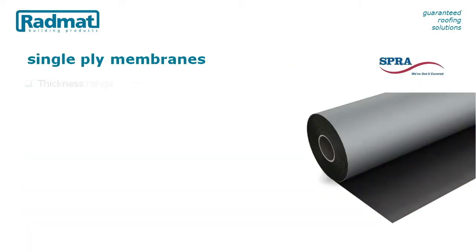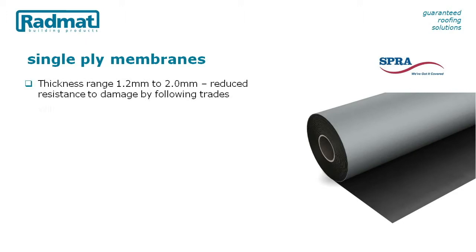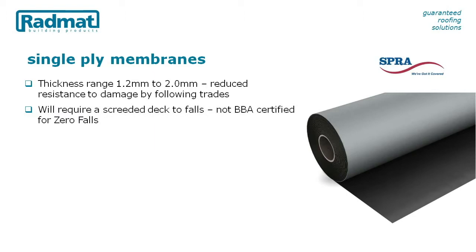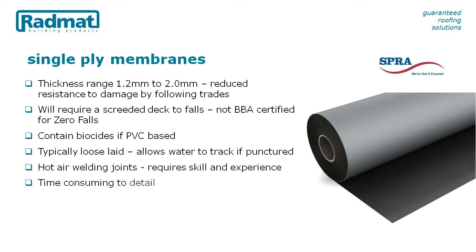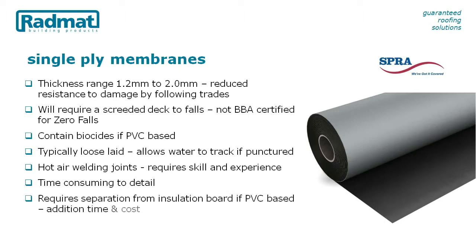Single-ply membranes are mostly used in warm roof applications, which is probably where many of you have used them. Suppliers of these products will also specify them in inverted roof applications, especially when it is the only product type they offer. When considering a single-ply membrane for inverted roofing, check the thickness specified and the puncture resistance offered by that thickness or product. The membrane will be trafficked during installation, and it's important to avoid damage for obvious reasons.